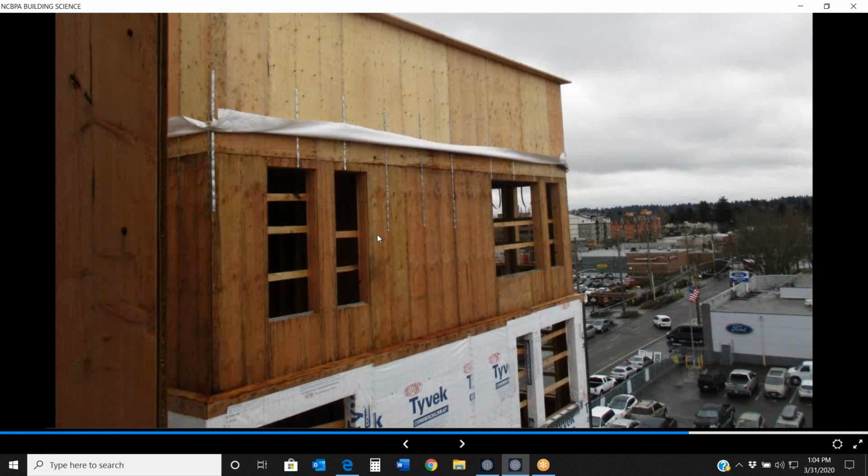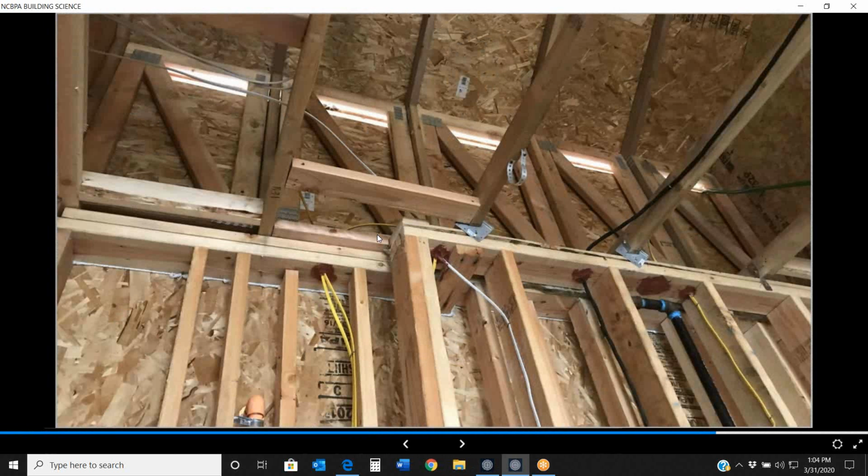This is an example, and it's just one way to do it, of how that air barrier was pre-stripped underneath the parapet. The roofing manufacturer's air and vapor barrier to the wall WRB was stripped in underneath, and the parapet was installed inside. Do that, and we need to have a vented attic, which sometimes we do. We want to make sure that we're really isolating that space.